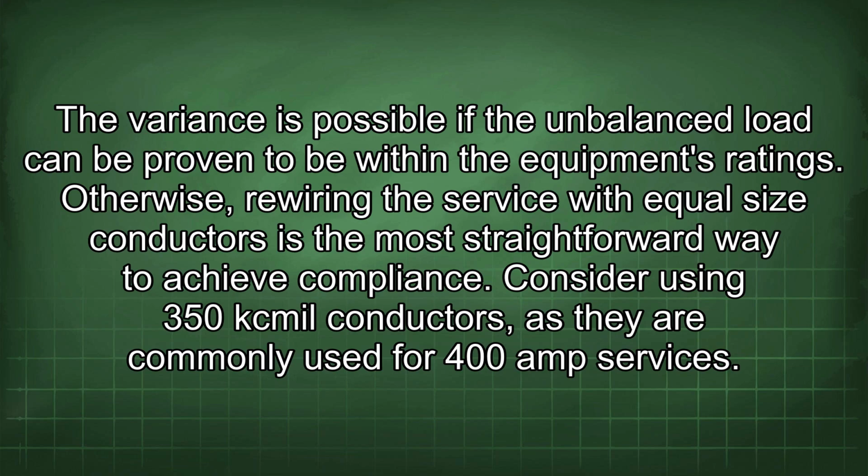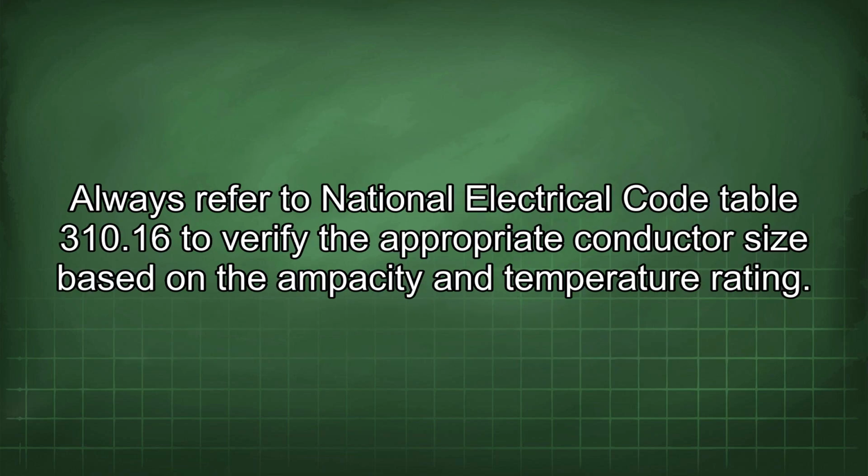Consider using 350 kcmil conductors, as they are commonly used for 400 amp services. Always refer to National Electrical Code Table 310.16 to verify the appropriate conductor size based on the ampacity and temperature rating.